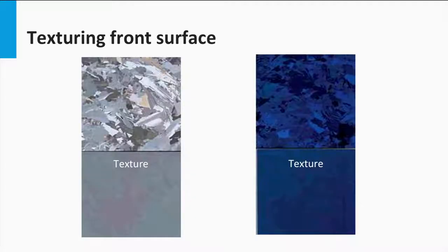Here we see a flat multicrystalline silicon layer with and without silicon nitride. Under these wafers we see two wafers with and without silicon nitride layers as well. The only difference is that the two wafers at the bottom have textured surfaces. The wafers are placed in the same illumination conditions as the flat wafers. By eye you can already see that these surfaces are darker and therefore reflect less light.